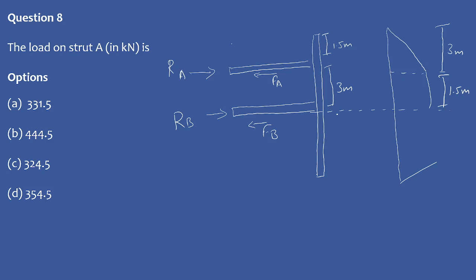Now the one key point here is that this point is basically the hinge. We know from the property of the hinge, or at the pin end, we can take the moment as 0. If this is your end A and this is your end B, the moment about B can be calculated from the lateral force from this part and this part and the reaction provided by A. So sigma MB is basically 0.